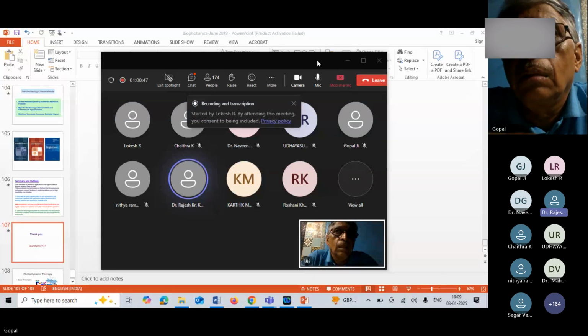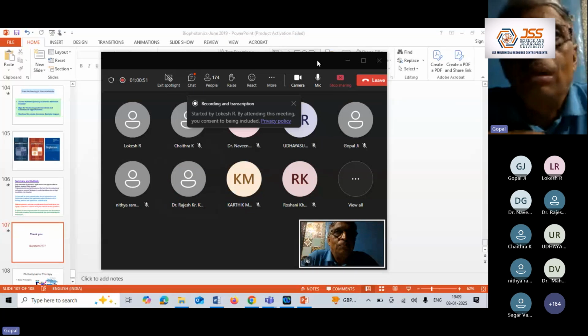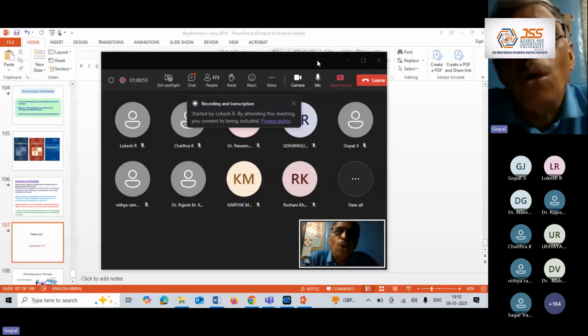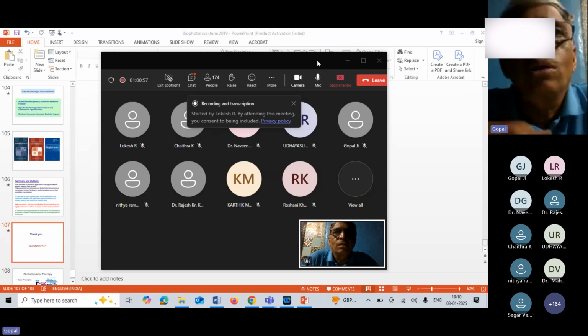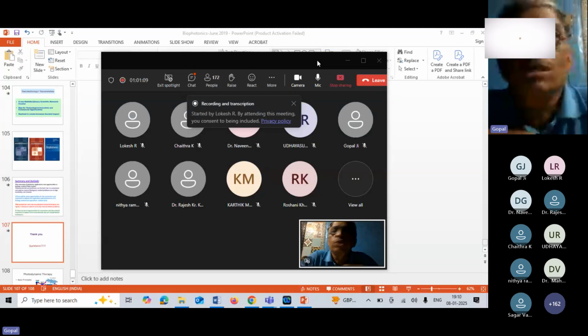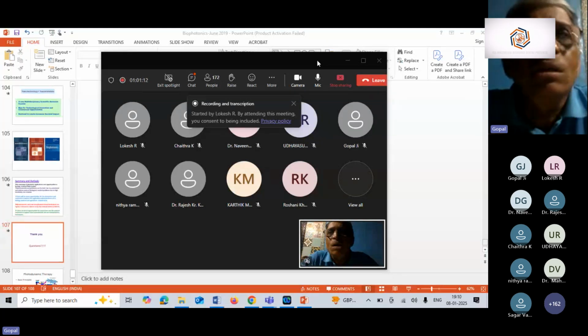Are these techniques useful in this case? Sol-Gel is better. CVD, again, is a higher end and longer technique. Sol-Gel is very handy and you can use it in simple chemical laboratories. CVD needs very high vacuum and is mainly for electronics, like making memory chips. For biological, Sol-Gel is okay.